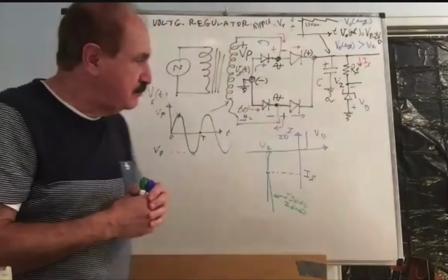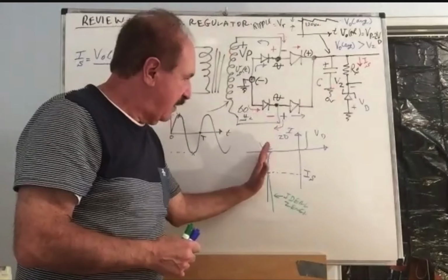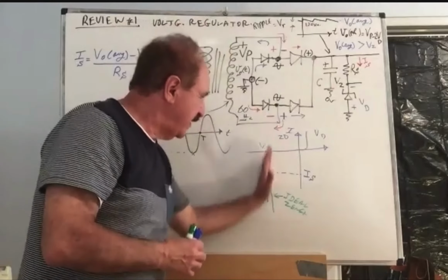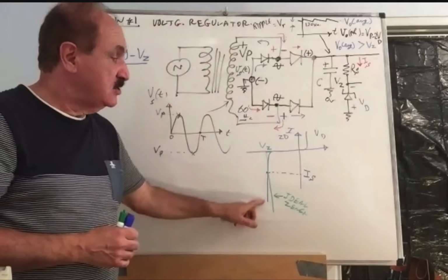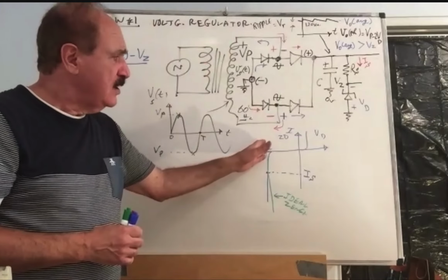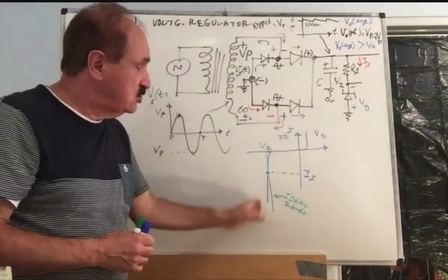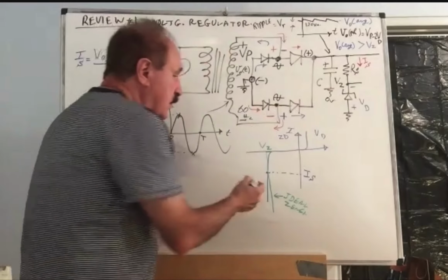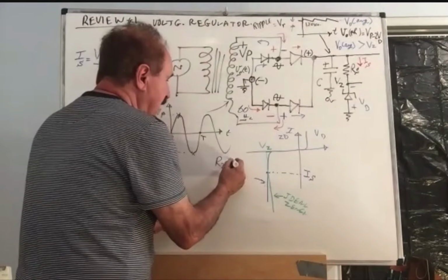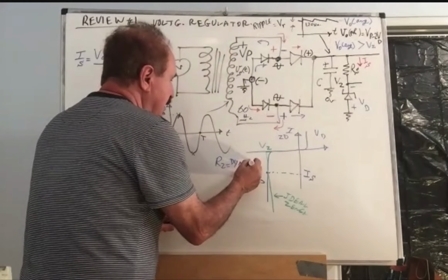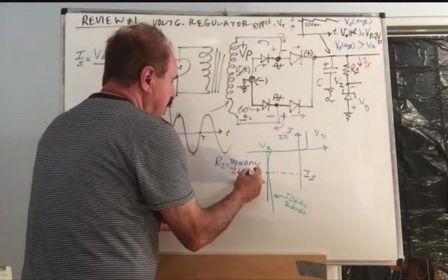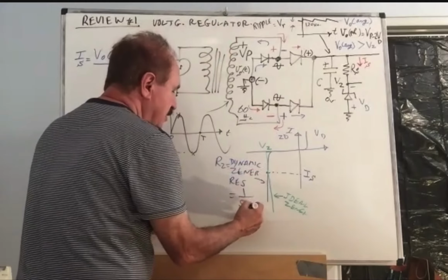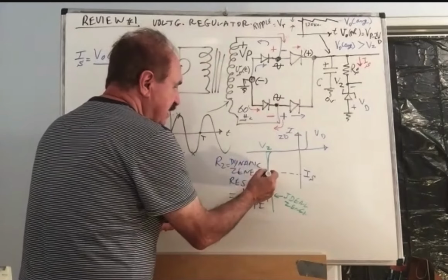Zener diode. But generally, the Zener diodes have this kind of steep, but with some finite slope, which speaks of a Zener resistance. So diodes, generally Zener diodes, tend to have some kind of a dynamic resistance. Dynamic resistance of the diode is here, RZ, the dynamic Zener resistance, equal to 1 over slope. 1 over slope of that blue line.